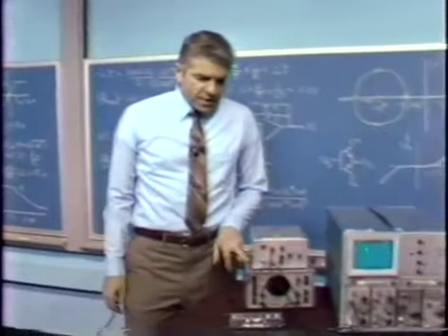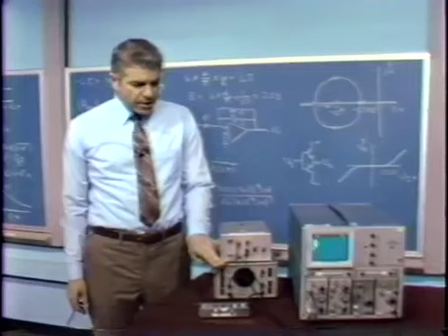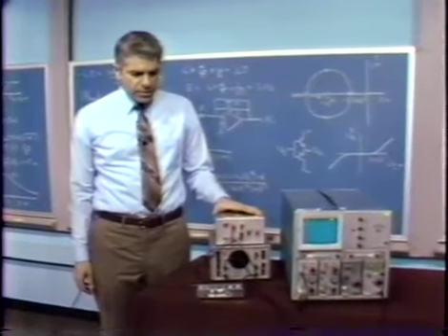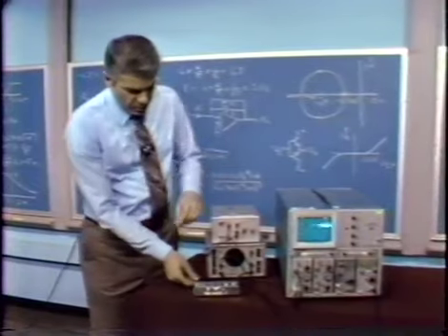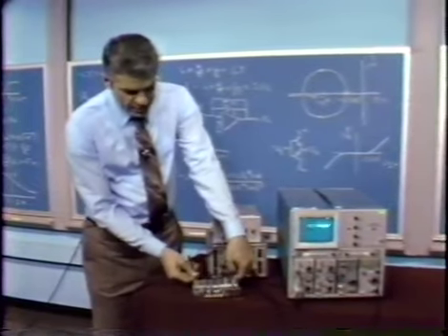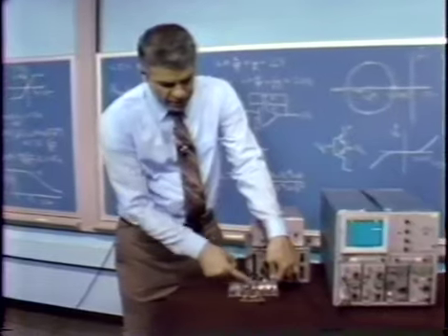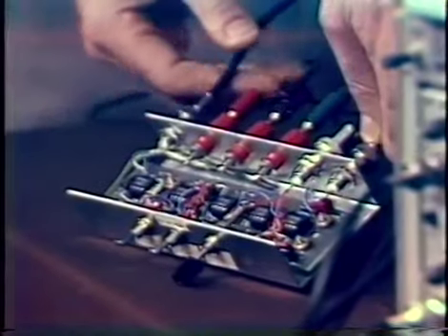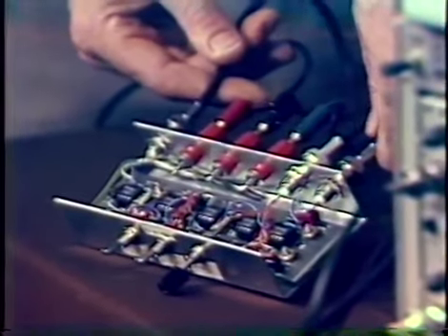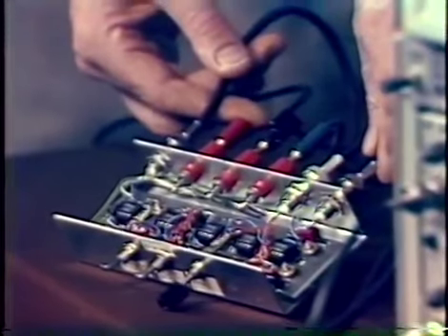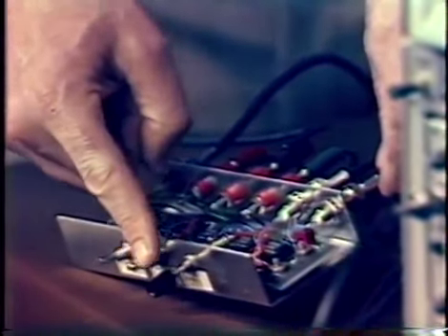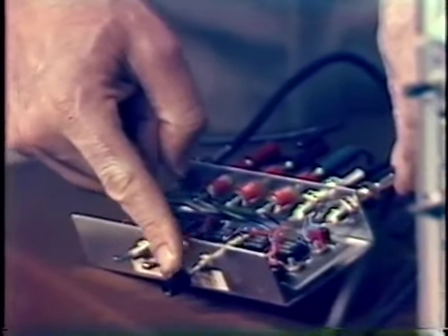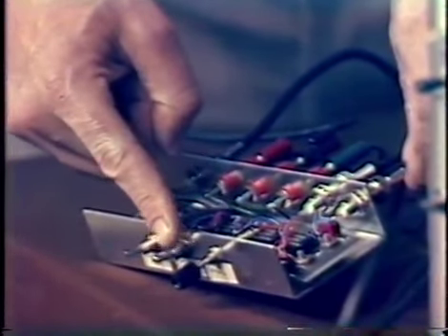What we have here is, again, the usual test generator, a power supply to power our setup, and we have the actual conditionally stable system here. We see 5 operational amplifiers ganged up, so they perform the functions that we showed in the actual schematic. We have the potentiometer that varies the magnitude or the gain, the quantity A naught.